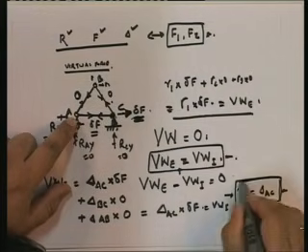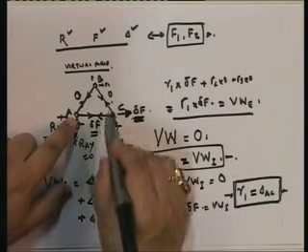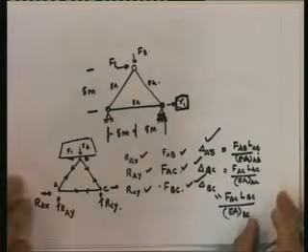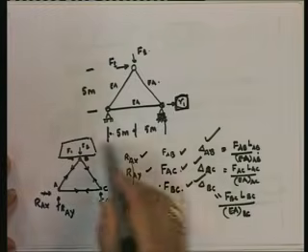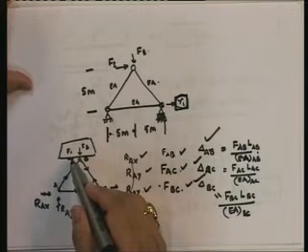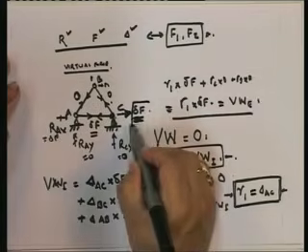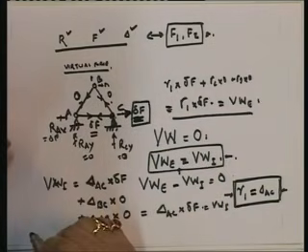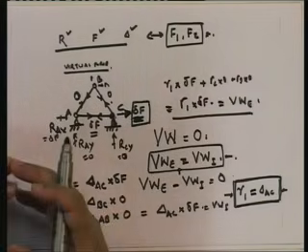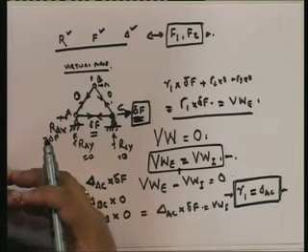You see, the method of virtual work has given me a geometry by actually solving two equilibrium problems. The first one was the real equilibrium problem where you are subjected to the real loads, and the second one is the real structure subjected to the virtual force, virtual load. This in a sense is how to use the virtual force method to get geometry of a structure.